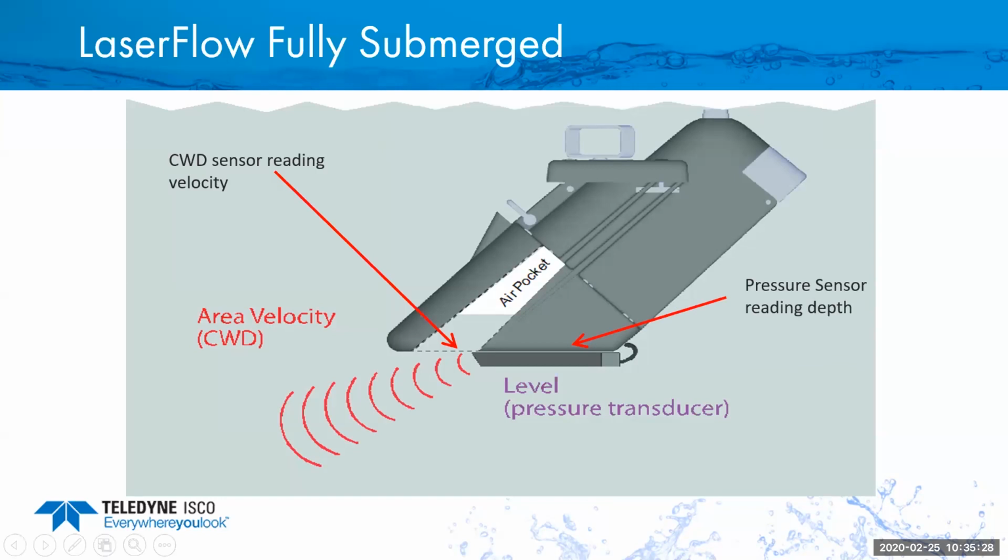Us and everybody in the industry will have the same issue unless you calibrate it at a different level. The neat thing about this one is it's mounted upside down. The nose of the laser is typically mounted at the crown of the pipe. So now we are reading a higher velocity because we are able to see where that peak velocity is. While this is not a perfect flow condition, the laser, coupled with the AV sensor, does a pretty good job on that.